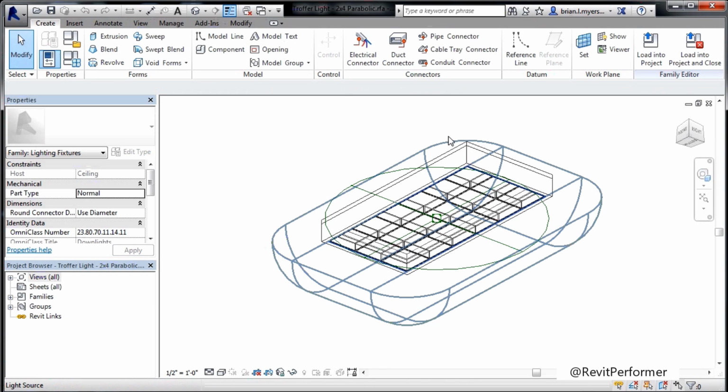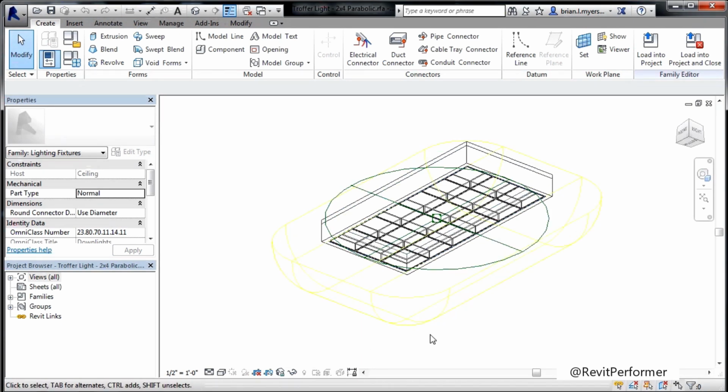And for this light fixture, we'll see this yellow box. If you ever edit a light fixture and you see a yellow box, that means that light fixture is casting light. That'll help you out. If for some reason you've put in some light fixtures, you do a rendering and the room's completely black, the first thing you should always do is select a light, edit it, and then take a look at it and see, is it capable of casting light?